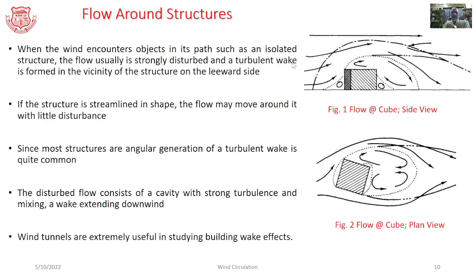So, when these winds encounter obstacles in their path, say some structure, this flow is considerably disturbed and some turbulent wake is formed in the vicinity of that particular structure, causing eddy formation on the leeward side.